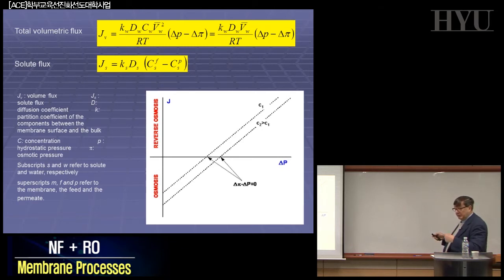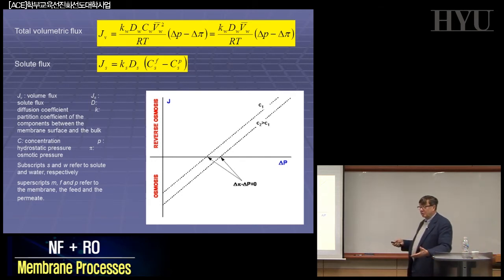And this linear function with the concentration. If the concentration in the solution is increasing, delta pi is increasing. And that means the driving force is decreasing. Now, when you have your membranes and the membranes start to work, in a good membrane with a high level of selectivity, water is going across the membranes. But salts don't go across the membranes.